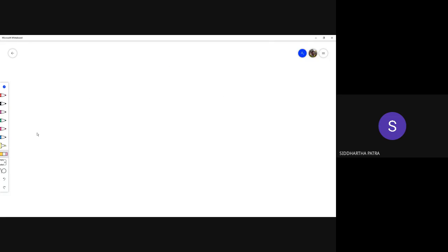Okay, so far we needed the geometry. Now from this point onwards we don't need the geometry. We have parameterized everything. Okay, the coordinates, the degrees of freedom, we have parameterized everything. Okay, so if you recall, your N looks like this now: xi 0 eta 0 1 minus xi minus eta, 0 0 xi 0 eta 0 1 minus xi minus eta.